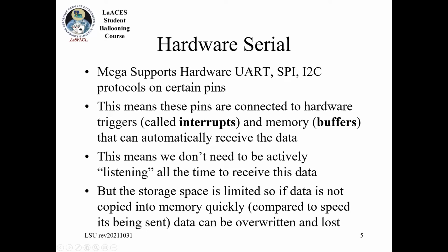That's the serial 1, serial 2, and serial 3. And then you really only have 1 set for SPI and I2C. But those are your hardware serial protocols on those pins. When you look at the pinout and it says SPI or I2C, it means that there's hardware on those pins.